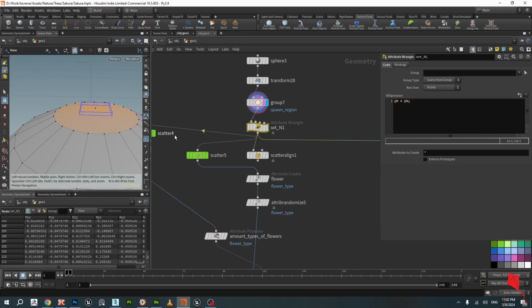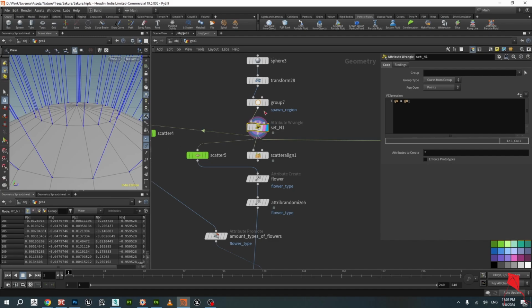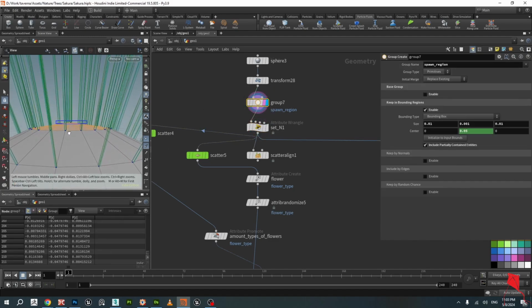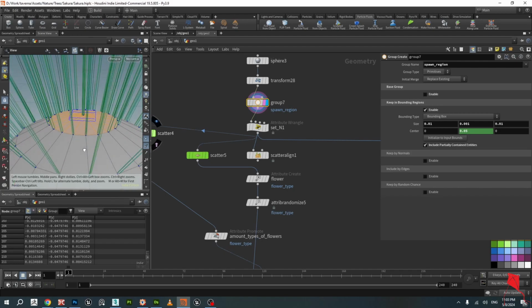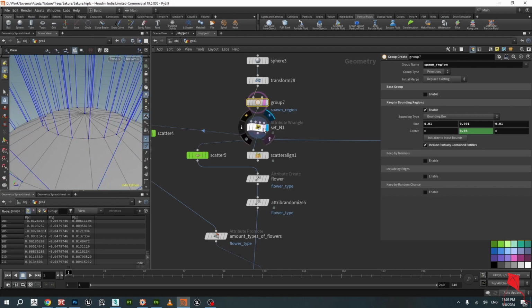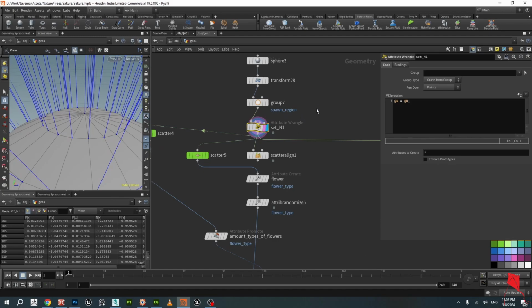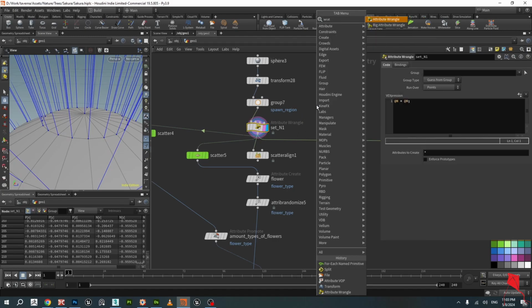Normally normals are attached to vertices, but I wanted to attach normals to points. And so here, if we turn on normals over here, we can only see vertex normals, which is the standard way. But with this little command, attribute wrangle, so just start typing wrangle.